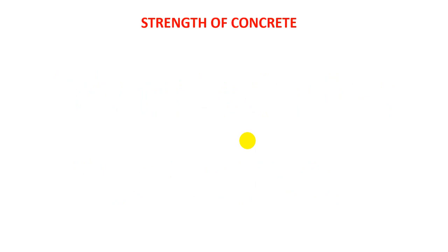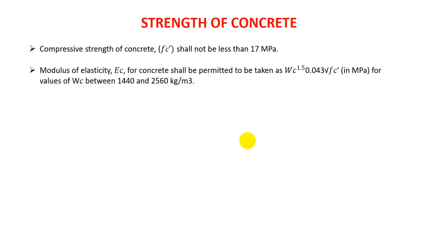First of all, we will see the strength of concrete. The compressive strength of concrete shall not be less than 17 megapascal. Clear? Then, how can we calculate our modulus of elasticity?